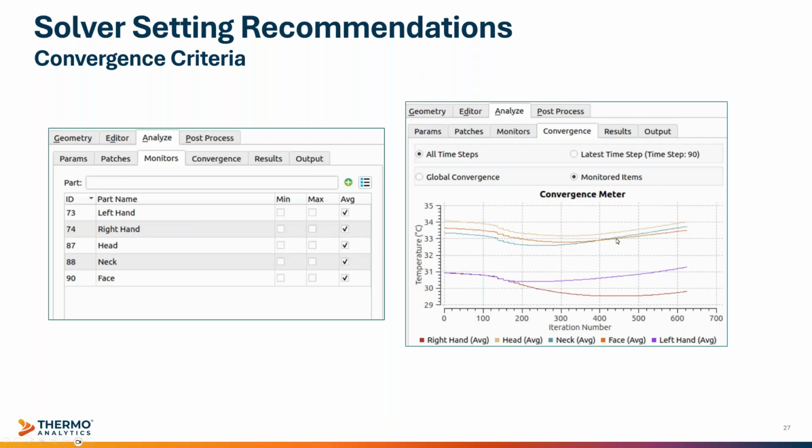These lines are fairly smooth, which tells me that these are converging well. If they were dramatically oscillating around, that would be a little suspicious, and I might want to check the boundary conditions on those parts or go back to the advanced parameters and make them more conservative.